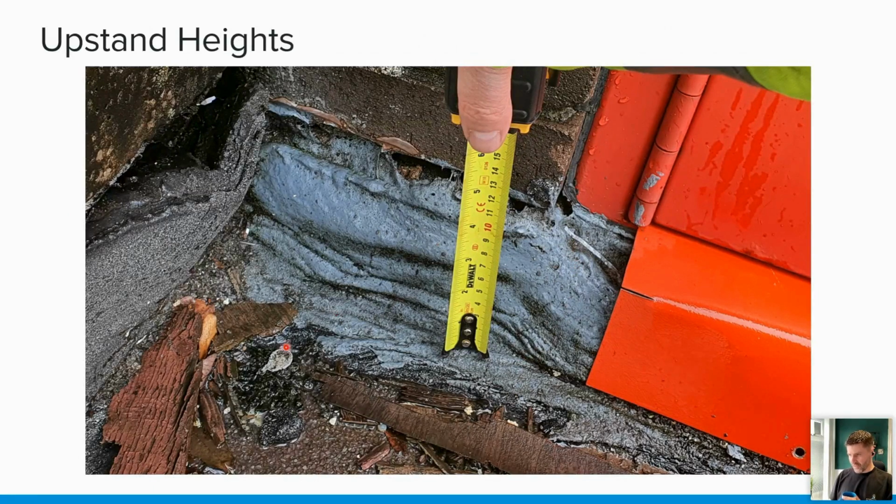So if we were to thermally upgrade this roof, we'd need to have done a core sample, obviously, to establish what the existing thickness is, and is that insulation in good condition so that we can put more insulation on top, or does it need stripping back to the deck, and do we need something around 130 millimeter thick insulation? So then, does this door then need replacing? That would tell us within our survey.